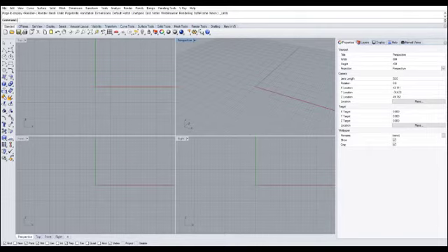So here it goes. To import our AutoCAD drawings into Rhino, you want to go to File, go to Import, and find our AutoCAD file, which was this one. I know in your video it says import unreferenced layers, import unreferenced blocks, and import line types were unchecked, and they're absolutely right.